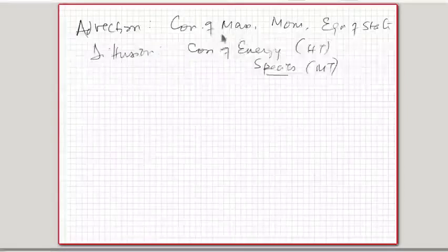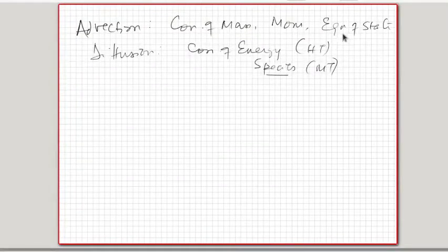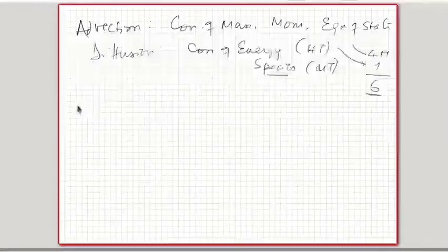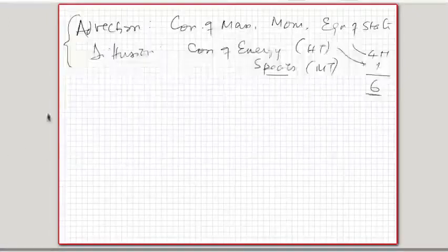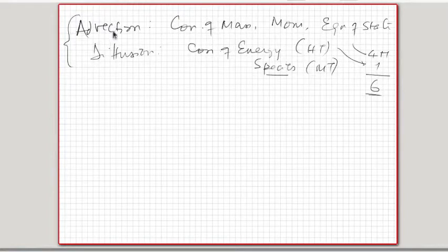Okay, so the combination of these maximum of 4 plus 1 equation and this one equation would actually be a total of 6 equations that need to be solved, and we will soon see, you might have seen it as part of your first course in heat and mass transfer, that the conservation of mass, momentum and energy are all partial differential equations, because you deal with physical or spatial dimensions more than one, and also deal with time when there is a transient. So you normally deal with partial differential equations when you're dealing with these.